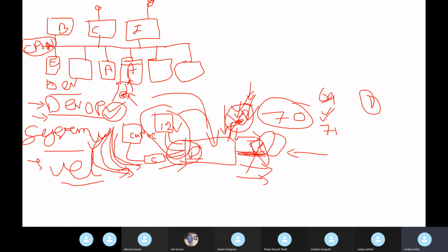One programming language called CAPL script. CAPL is Communication Access Programming Language, used in the network by using a software. For example, if you connect the software to the complete network, at vehicle level also, using CANoe software you can send CAN signals.